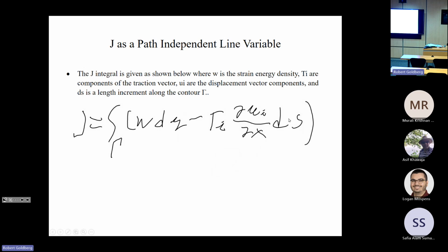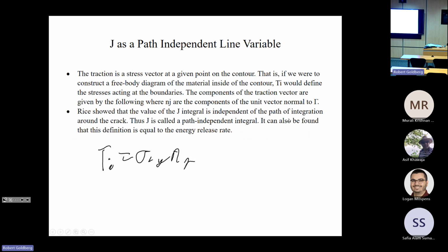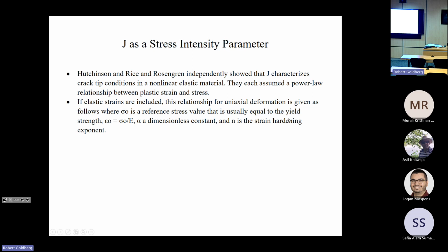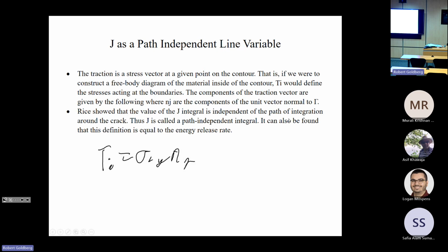and applying the other definitions that we talked about to do all these calculations of strain energy densities, etc., and variations in coordinates and in displacements, and we can use that to compute our strain energy, to compute our nonlinear strain energy release rate.